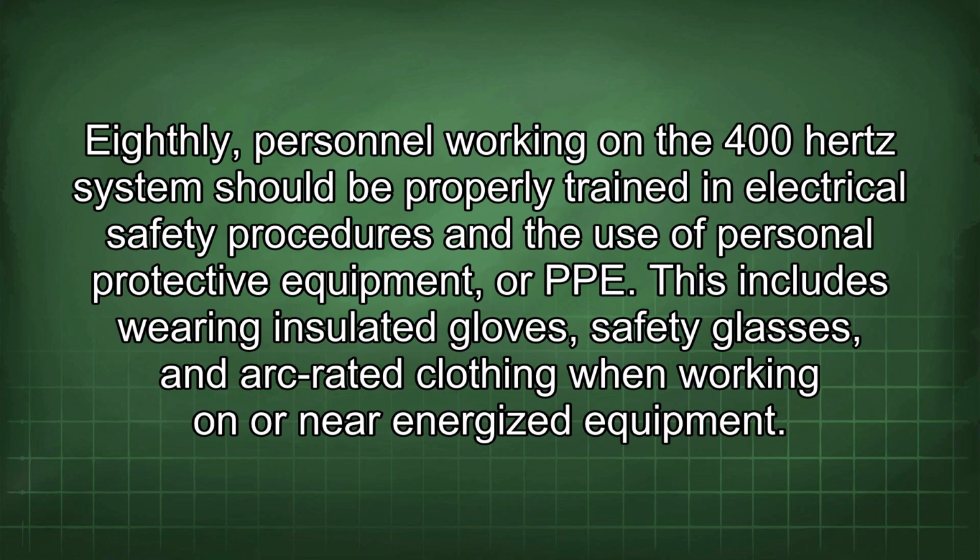Eighthly, personnel working on the 400 Hz system should be properly trained in electrical safety procedures and the use of personal protective equipment, or PPE. This includes wearing insulated gloves, safety glasses, and arc-rated clothing when working on or near energized equipment.